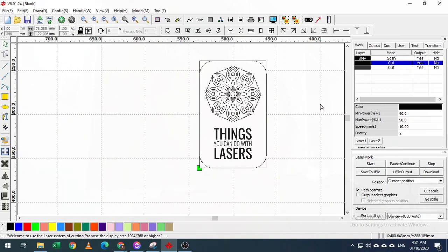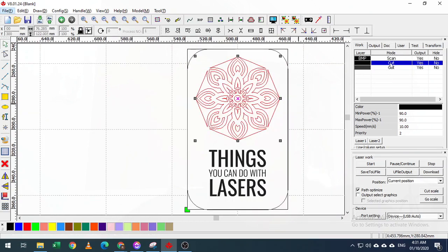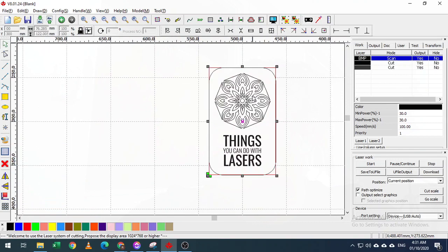So what we need to do is cut from the inside and then slowly work outside. So from here, if you want to confirm, you can just right click this, and as you can see, this would cut this first. So first the machine would scan, next the machine would cut this part, and then lastly this part.